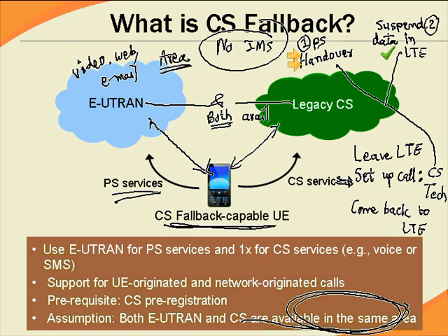It's possible that in future, we may have those dual transceiver UEs, meaning you have one transmitter receiver for 1X, and a separate transmitter receiver for LTE. So then our UE can be on two technologies exactly at the same time. Then you can do voice on 1X or UMTS and data on LTE. That is done if the UE is capable of supporting two technologies simultaneously.